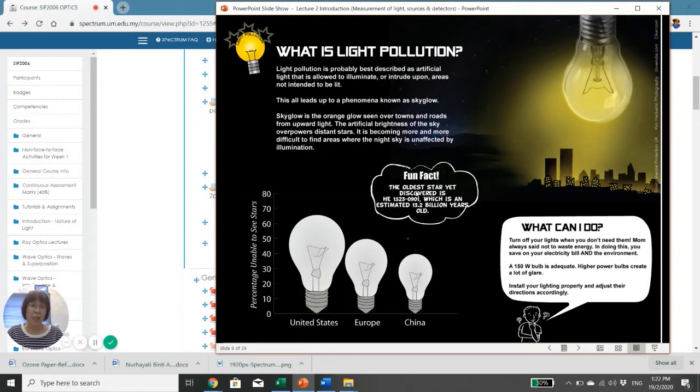In the olden days with incandescent bulbs, for a simple room like our lecture hall, we would need probably about 2 incandescent bulbs, each of 120 watts. But now, with fluorescent lamps, if we have about 6 pieces at probably about 18 watts each, let's round it to 20, that is 120 watts, about half the amount. And with further improvement in lighting, like using LED, it can be reduced even further.